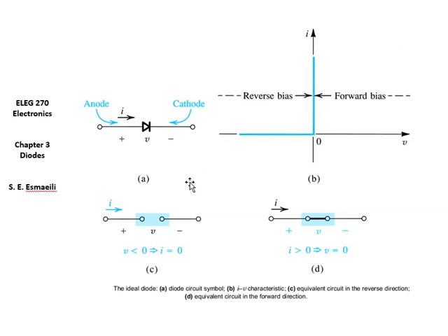Look, if you want to find a way to memorize it, the diode itself looks like an arrow shape. So it passes the signal towards the arrow, but if you bias it in the reverse direction against the arrow, it's not going to pass it. It's going to stop it. So in one direction, let's say here, if the current I is greater than 0, it means it's going towards the arrow direction. It's working like a short circuit. If you are biasing it from the other direction, from the reverse side, it's working like an open circuit. This is called an ideal diode.